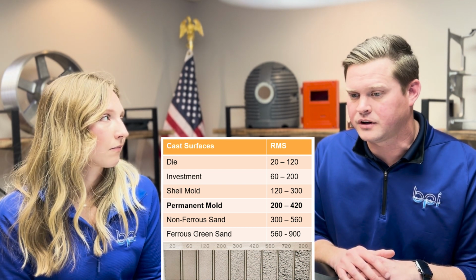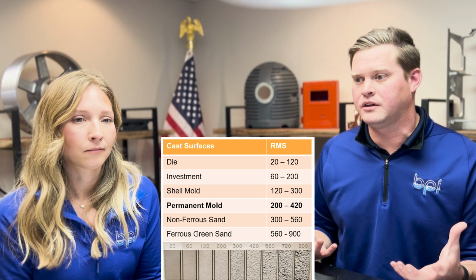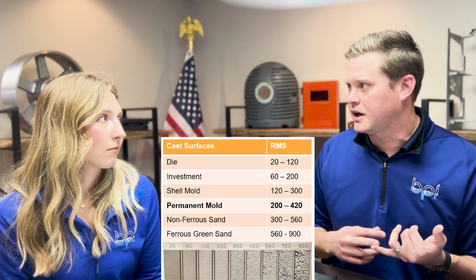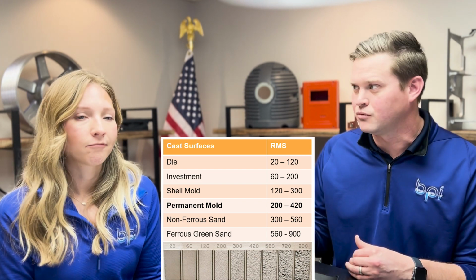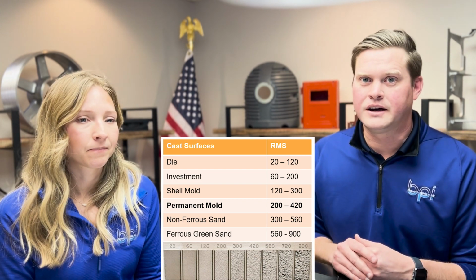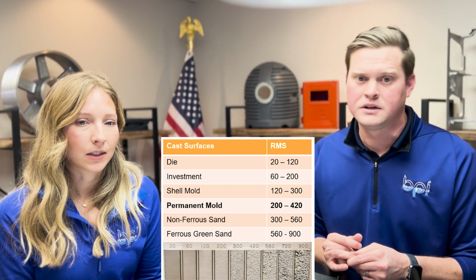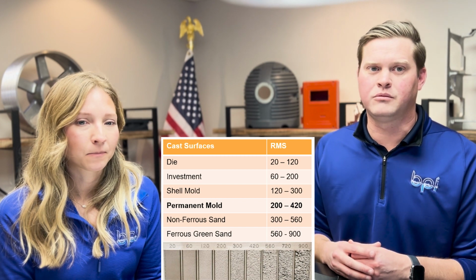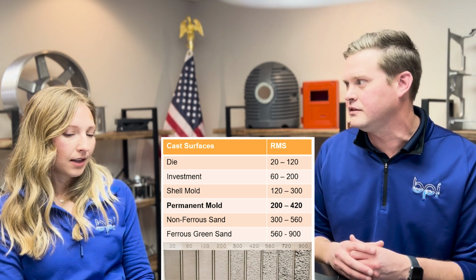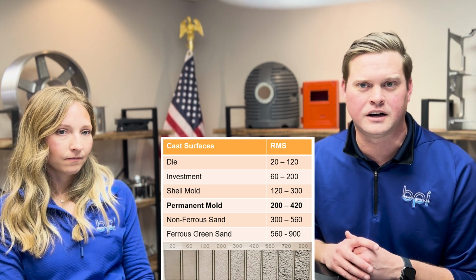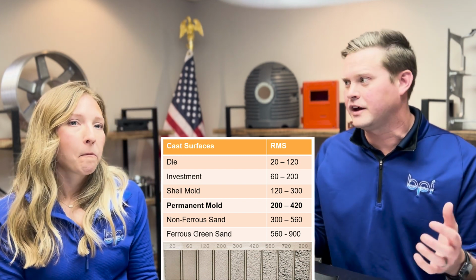We have a number of products that are in the 120 to 200 range, but we have processes here that allow us to get that coated application to stick, and get that surface finish to be the end expectation. Robotic polishing in general, shot blasting, so a bunch of different opportunities to get it into that range as well. And with the goal in mind, where do you need to be? What surface finish are you requiring, and what does your customer see? Do they see this in front of their face at their height, or is it something hidden that doesn't need that? With all that obviously comes cost.